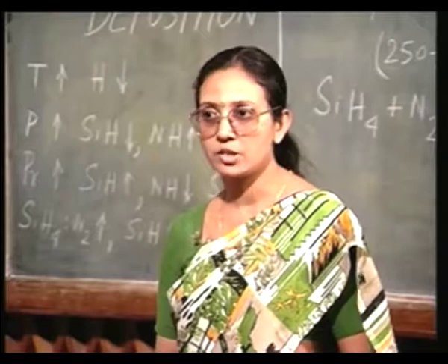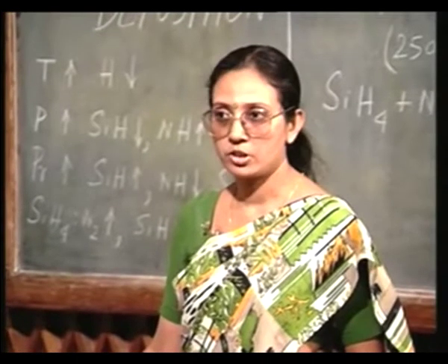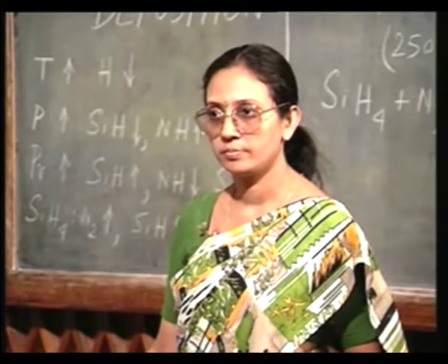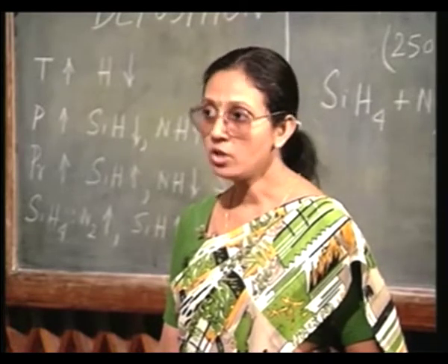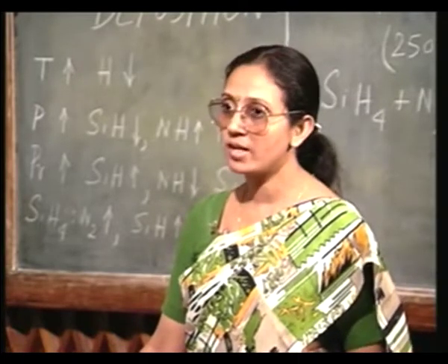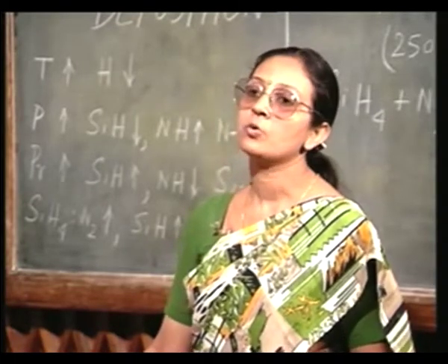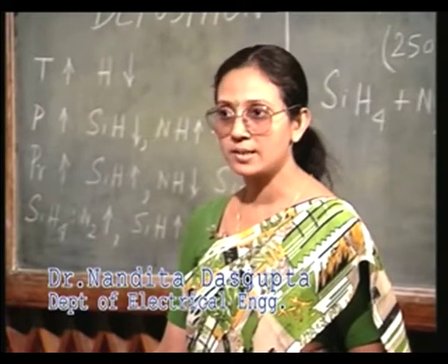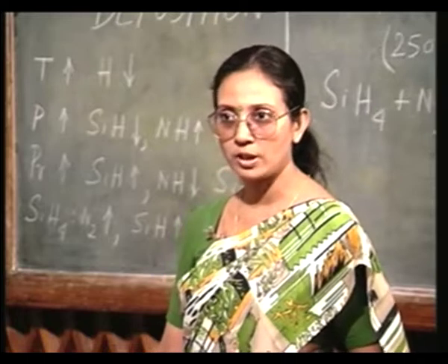Now, in case of metallization, in general, we have 3 types of metallization. What are those 3 types? First is the ohmic contact. You know, whatever regions you have, emitter, base, collector, source, drain, there must be an ohmic contact. Next, if you have MOS devices, you must have a gate. Remember, nowadays for almost all MOS devices, the gate is no longer a metal, but it is polysilicon. Okay. So, the next is the gate metal or the gate poly, to be more accurate.